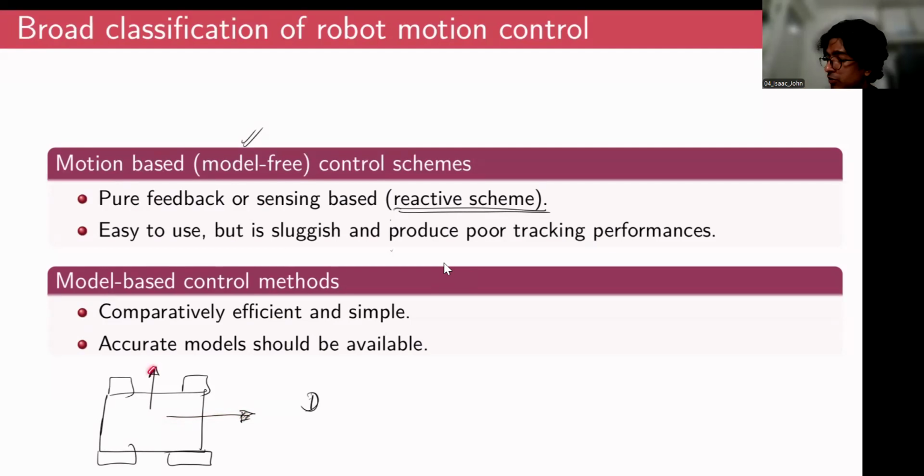So if the robot had some inertia to move along the lateral direction, that dynamics would be captured by this inertia matrix. As a result, if the robot has some inertia to move in this direction, but the robot has to move, the control input would be amplified. The control input would be somewhat higher if the robot has to move in this direction.